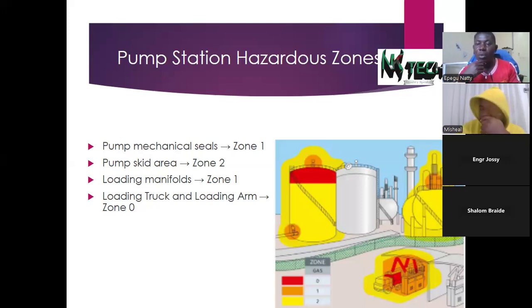Definitely they will listen to you, because you tell them that this equipment is not meant to be positioned in this region. You can get your code from the IEC or the ATEX that we just mentioned, and then show them with evidence that, you see this code we have here, this temperature is showing that this machine is going to be operating hot, at about 300 degrees.